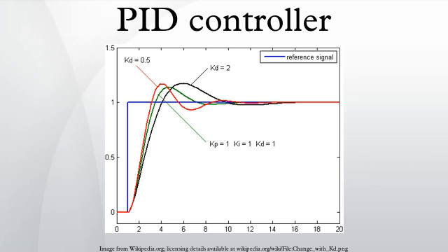Linearity. Another problem faced with PID controllers is that they are linear, and in particular symmetric. Thus, performance of PID controllers in nonlinear systems is variable. For example, in temperature control, a common use case is active heating but passive cooling, so overshoot can only be corrected slowly; it cannot be forced downward. In this case the PID should be tuned to be overdamped, to prevent or reduce overshoot, though this reduces performance.